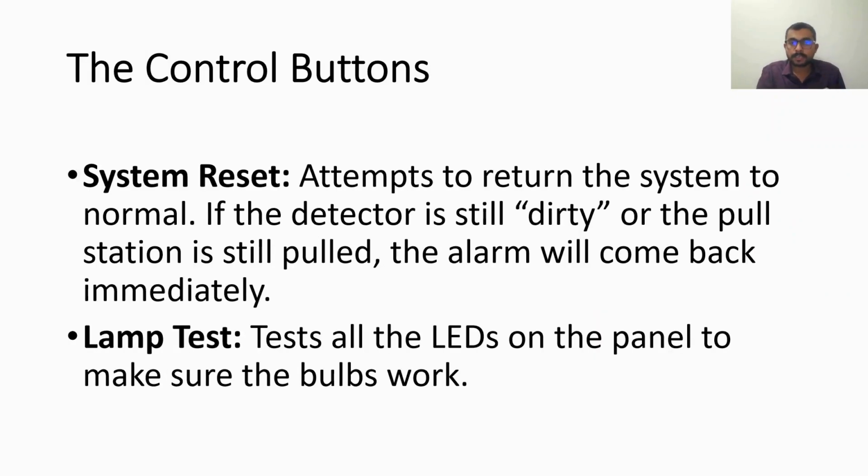Then comes the system reset. System reset is basically making the system go back to normal. That is called the reset button, the system reset button. If there is an alarm condition or a fault condition, and you have rectified the cause of the alarm or the fault, then you go back to the panel and reset the system. This is what the reset button is for.